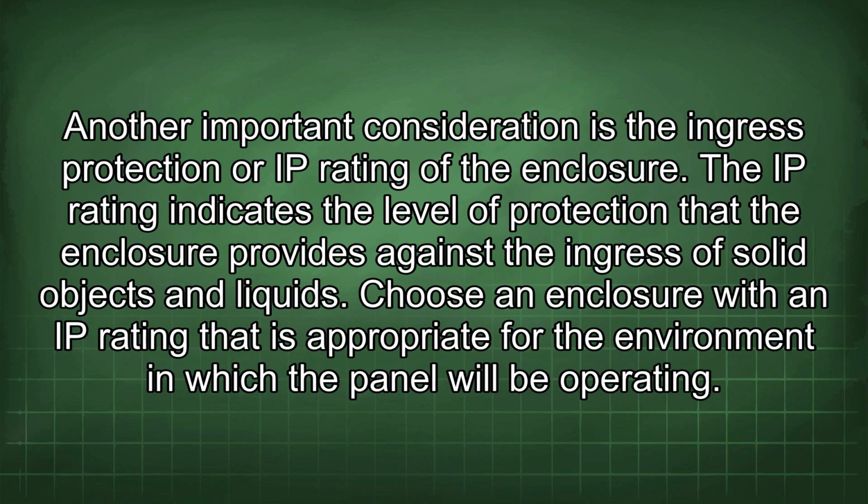Another important consideration is the ingress protection, or IP, rating of the enclosure. The IP rating indicates the level of protection that the enclosure provides against the ingress of solid objects and liquids. Choose an enclosure with an IP rating that is appropriate for the environment in which the panel will be operating.